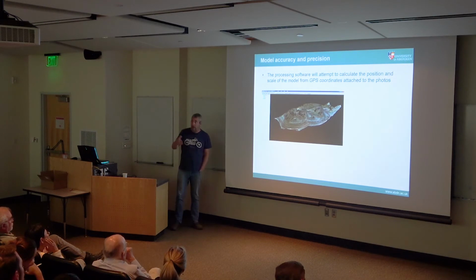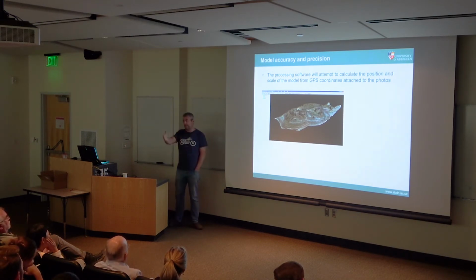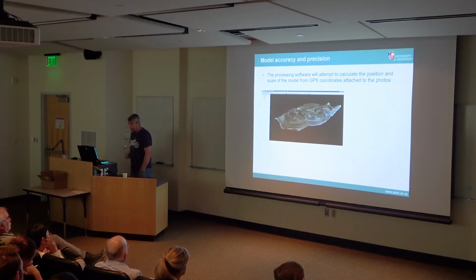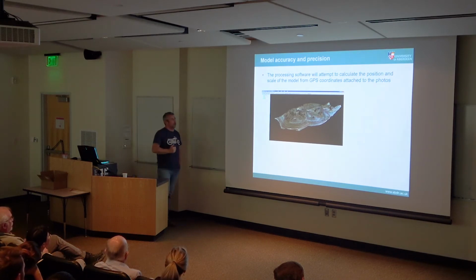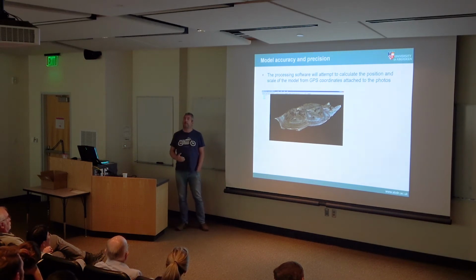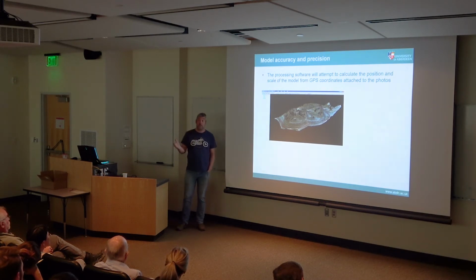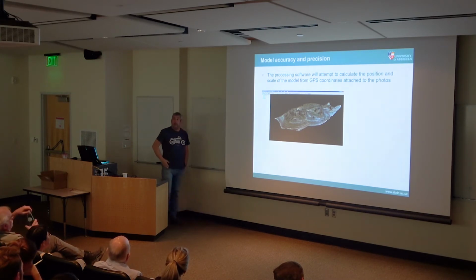So you can ask, how accurate is it and is it as good? The question we're always asked is, how does it compare to the LiDAR? So we've done lots of different benchmarking exercises to compare the 3D models you get from LiDAR to the 3D models you get from drones and so on. And then how repeatable are the models that you're getting from photogrammetry and drones? The bottom line, well, we published a paper on it if you're really interested, but especially as a sedimentologist or for anybody who's interested in relatively large-scale structures, the drone will give you a model that is fit for purpose.